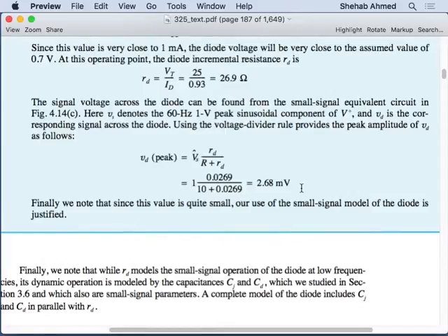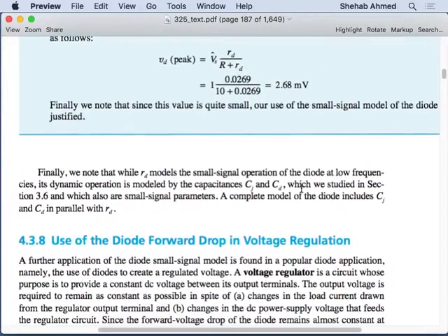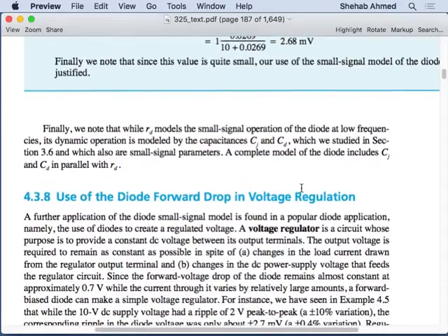So here our signal was what? Our signal was this VD. We attenuated it so that we can apply it in voltage regulation. I cannot really put a signal and amplify it using this diode application, using just a pure diode. That's where we will come in and try to see what we can do with a MOSFET and a BJT device here. But the idea is the same: DC operating point analysis, then small signal analysis. Yeah. So that being said, we just go.